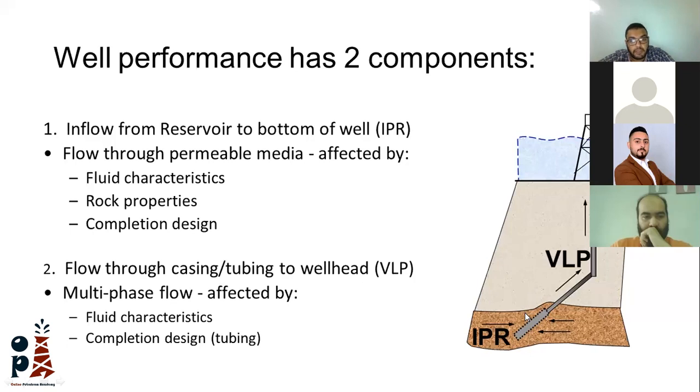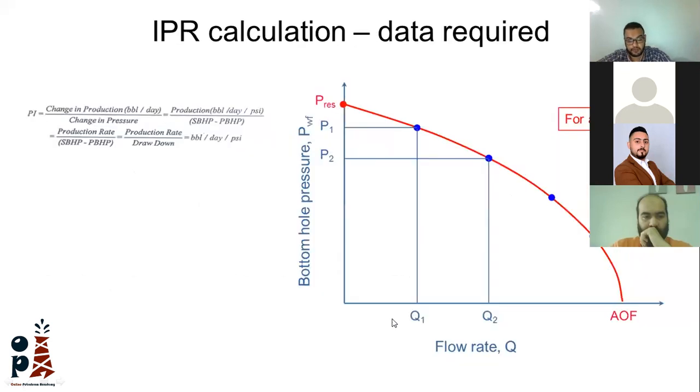Okay. So what's the next question? Ahmed Rashid is asking, what is the correct procedure to prevent sand production? Okay, for the correct procedures, there are curves that you enter. You see, I have, for example, the properties of the reservoir. There is a value called UCS, the compressive strength of the sand.